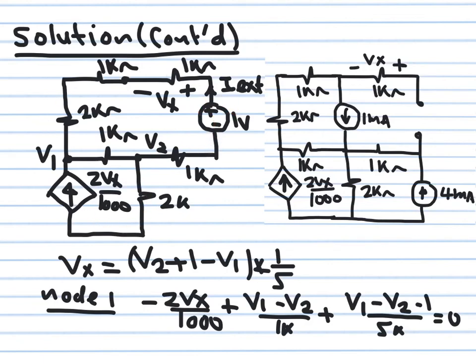So this is a circuit, and as I explained in class, sometimes I was able to keep this one as a symbol, as a V external. But if you want to use loop and nodal analysis, give it any value like 1 volt. The answer I'm looking for, R Norton, is 1 volt over I external. So this is a circuit.